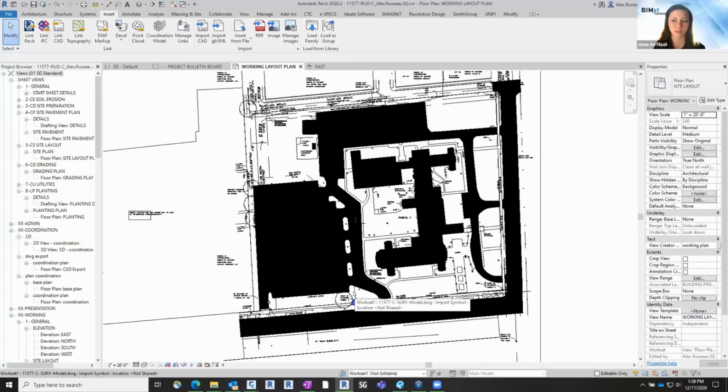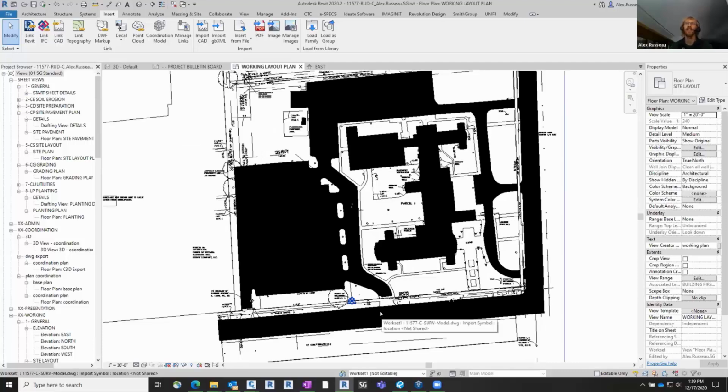And when you say a known point, do you mean something existing? Like you said, the point that you selected is a property line that would be easy to find, but would maybe a corner of an existing building be something that you'd want to select? What are some examples of a point that you would select? Yeah, worst case scenario, building corner, but not all buildings last, especially if it's an old one. You know, those could get moved. And oftentimes too, if you've got a survey stake trying to go up against a building, you're never going to get exactly there because the width of the rod that you're using is always going to be an effect.